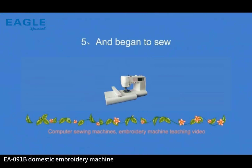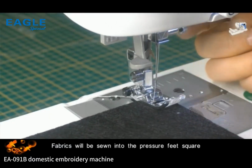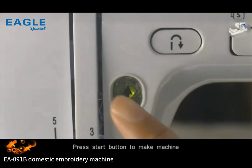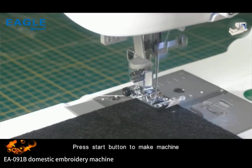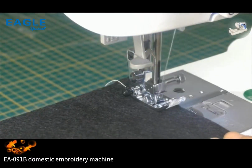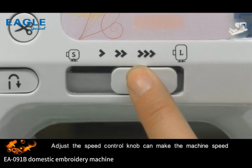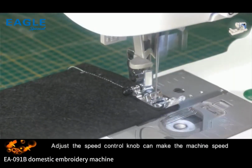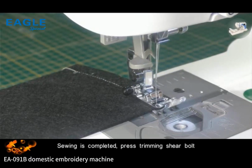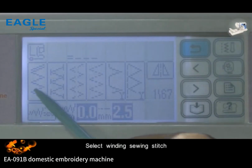5. Begin to sew. Open the power supply, and place the fabric under the presser foot. Choose the straight line stitch. Press the start button to run the machine. Adjust the speed control knob to change the machine speed. Sewing is completed, press the trimming shear bolt. Raise the presser foot, remove the cloth, select the winding sewing stitch.